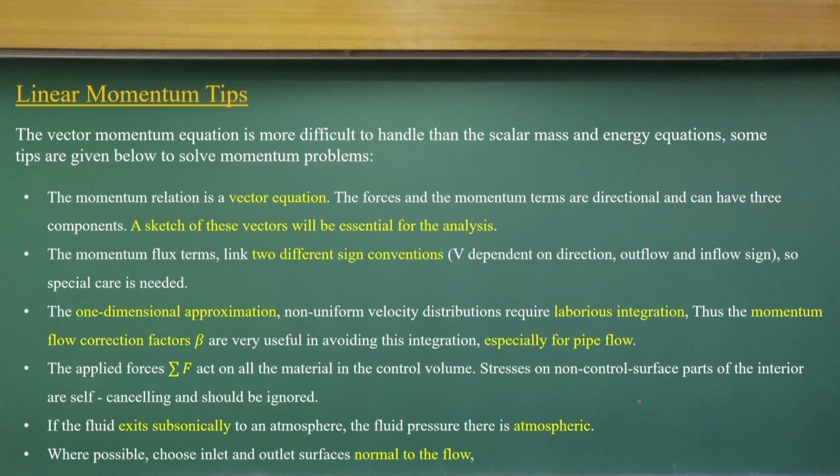Now, coming back to the tips when you apply the linear momentum equation. First, do remember that the momentum equation is a vector equation. It has 3 scalar components and directions. You can write it as an x-direction equation, a y-direction equation and a z-direction equation. Many times we do not resolve into 3 directions; we resolve the equation in only one direction to solve a particular problem. But we can resolve these momentum relations in 3 directions: x, y, z.